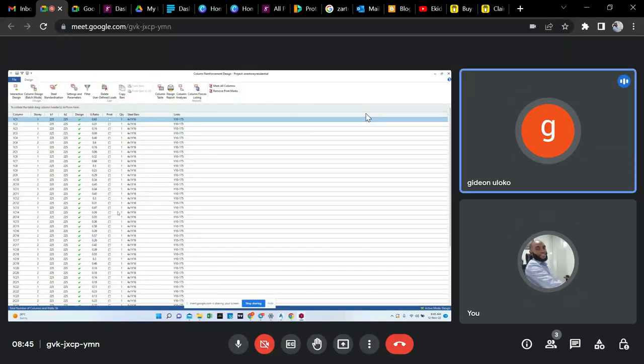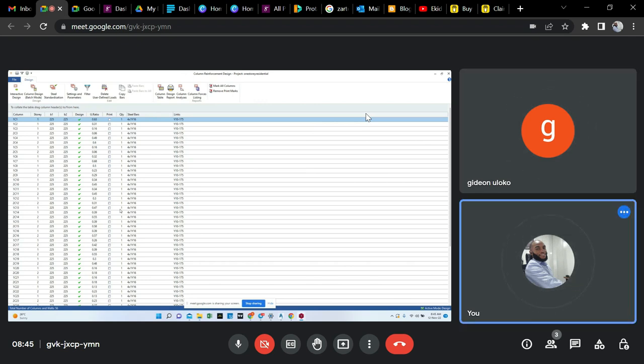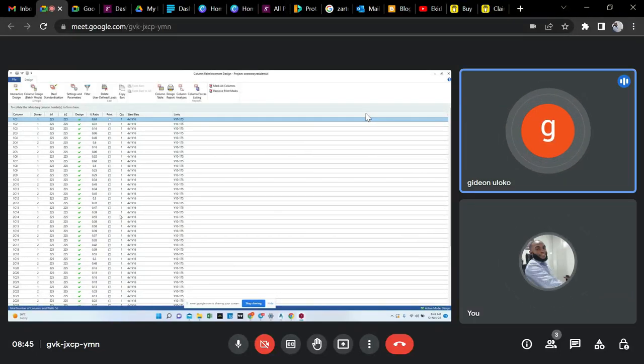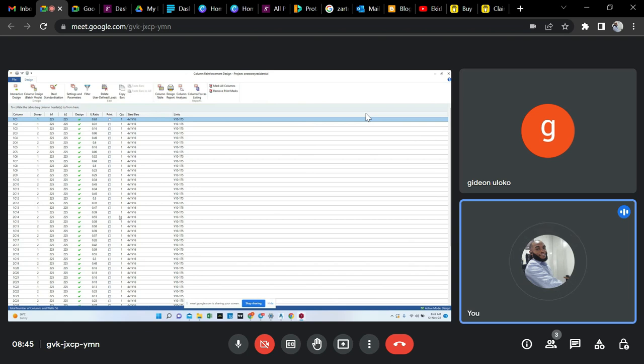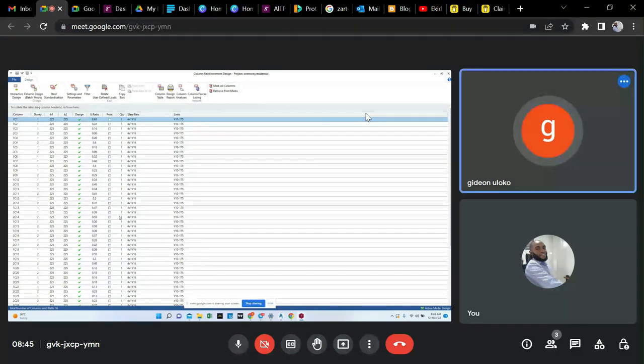Steel bar area, the steel zone, is on its own. But if you're having more than one point something value, that means the steel zone is trying to enter the concrete zone, basically having more steel than concrete. So what you should do is increase the size of your member, either your beam or your column, so that it can now separate itself. You understand?